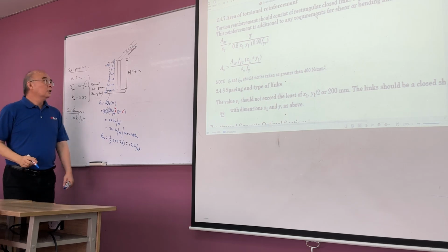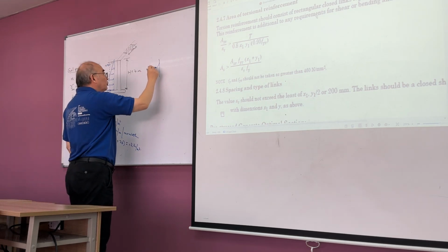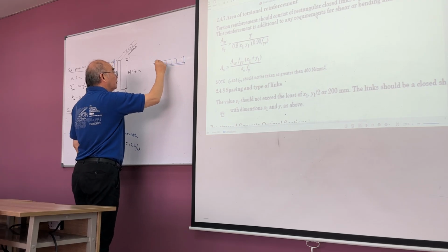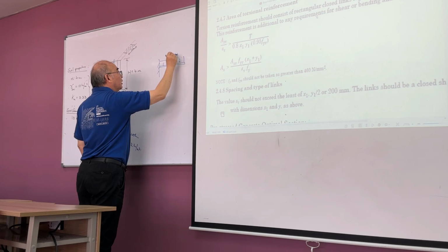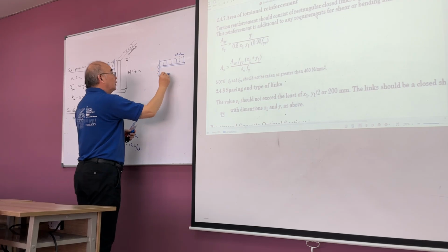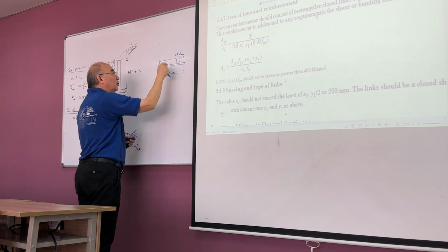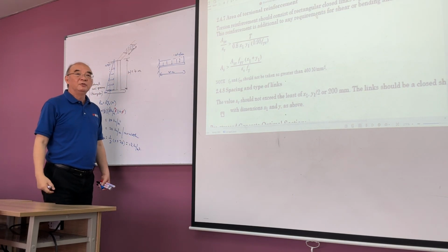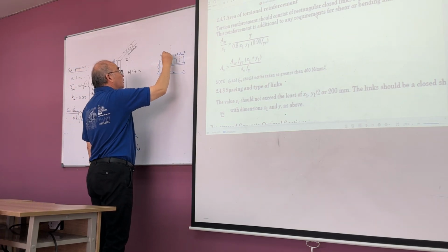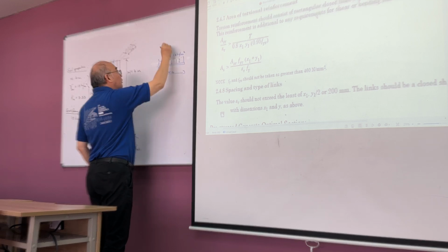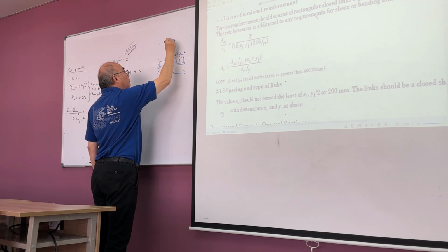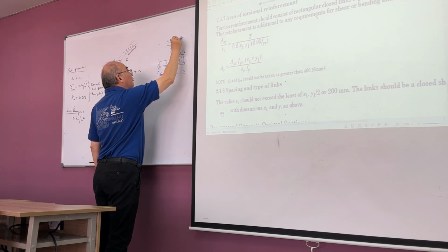Okay, so now you know how to do this. Let's say this is a beam here. Now I have this average uniform load, let's say 12 kilonewton per meter. So what is the total force? Total force will be 12 multiplied by 4, right? It will be 48. So the total force here will be 12 kilonewton per meter square multiplied by 4 meter.